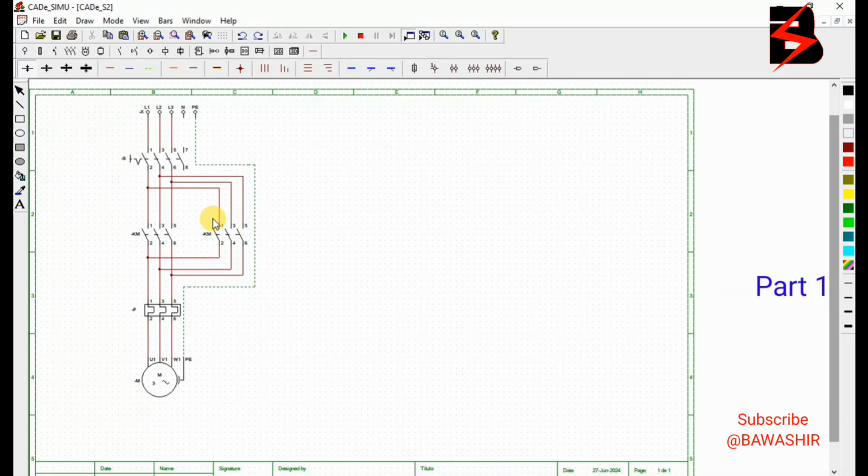So now when it comes to control, we have to design 2 different controls. We have to switch on contactor 1 independently in case we want clockwise rotation. Rather, we switch on contactor 2 separately in case we want anti-clockwise rotation. Take this into account. When you happen to switch on the 2 contactors at once, or switch on any contactor when the other one is on, look at this.